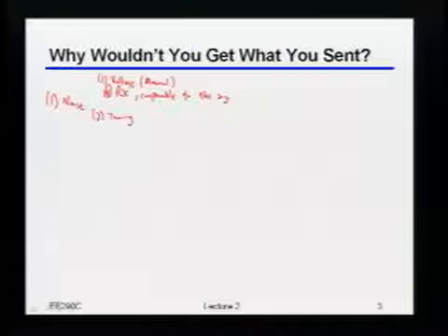So what's bad about inter-symbol interference? Like, what does it sort of do that makes you get the wrong bits? Your RC delay. RC delay. Your channel's like a low-pass filter, so when you have a change, it sort of smears it out, and then it can interfere with the next one. So what you said was, let's say I have a low-pass filter in my channel.